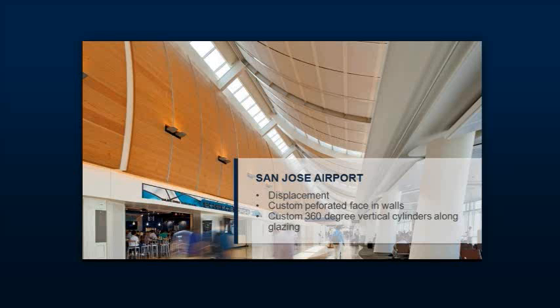At first blush, when I look at this, I thought, wow, we hid the diffusers behind the wood slats. And in fact, I spent a lot of time hiding air diffusion products behind wood products, to be honest. And I've recently put chilled beams behind wood slats of this type, linear slot ceiling diffusers. There's a lot of ways of moving air, but in this large of a void, displacement shines because I don't have any need to mix the air above the occupied level. It's a waste of energy to do so.